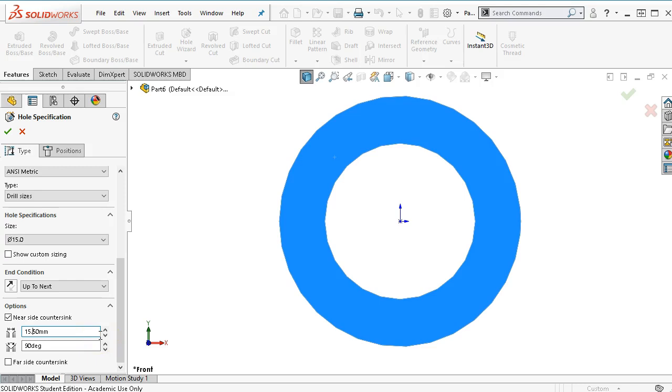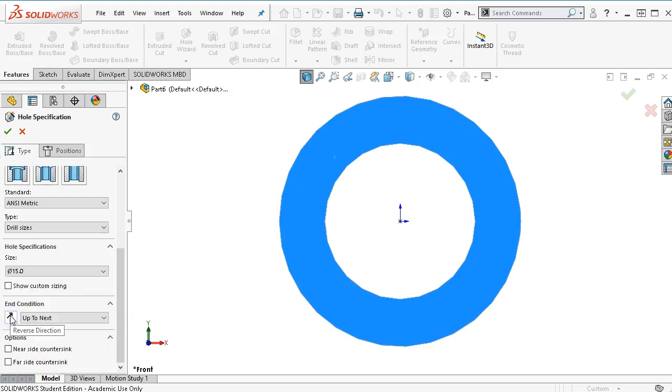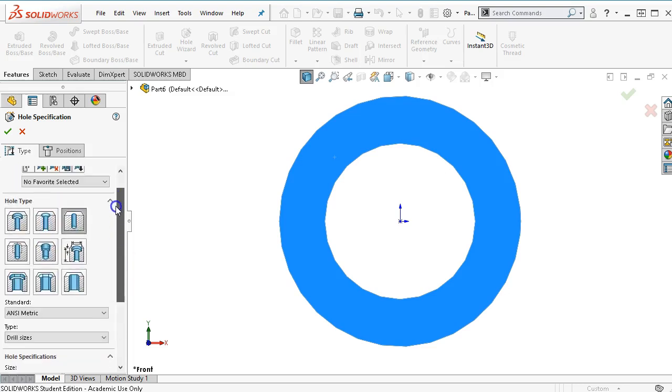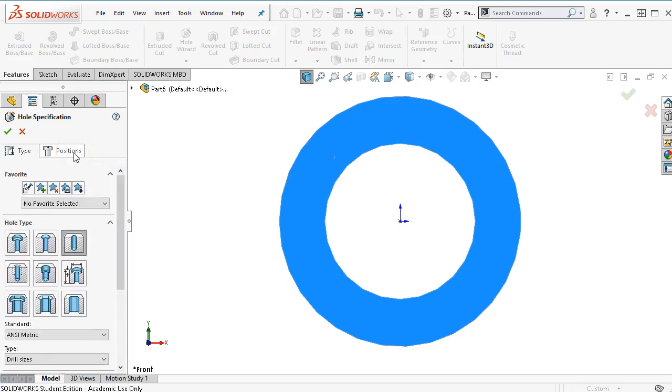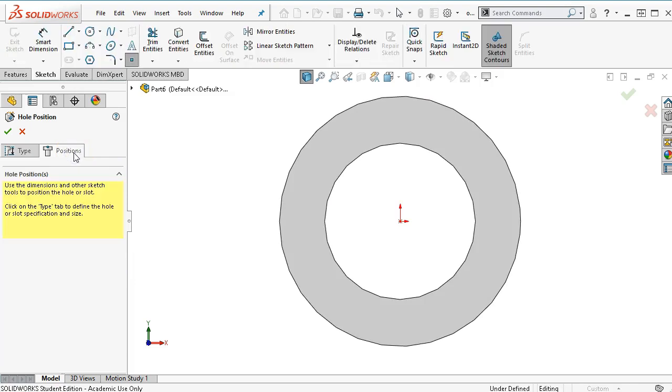If we did half a millimeter, that would be basically 10 thousandths converting back to inches, that would be 10 thousandths per side. And then a 90-degree or whatever angle we wanted to include. So the diameter of the countersink to the outside. Most of the time, I'm going to recommend that you call out an edge break somewhere on the print rather than including the chamfers unless they're necessary.